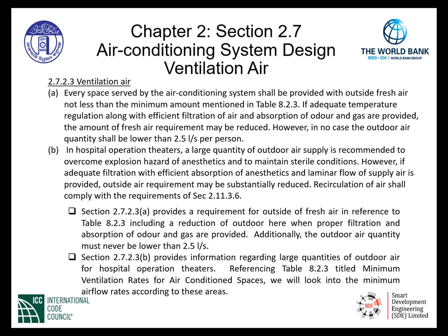However, if adequate filtration with efficient absorption of anesthetics and laminar flow of supply air is provided, outside air requirement may be substantially reduced. Recirculation of air shall comply with the requirements of Section 2.11.3.6.